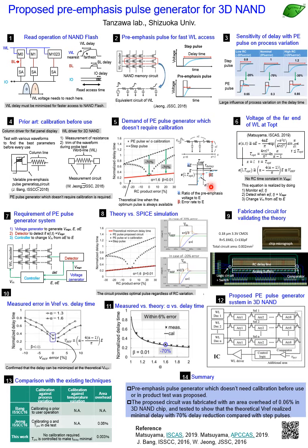What we want to do is find the voltage at the furthest node at t equals t_opt. That value is expressed by this equation, and you see no RC time constant here.